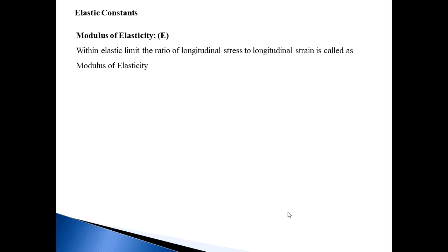First, modulus of elasticity. Within elastic limit, the ratio of longitudinal stress to longitudinal strain is called the modulus of elasticity. That means stress divided by strain, and it is denoted by capital E.